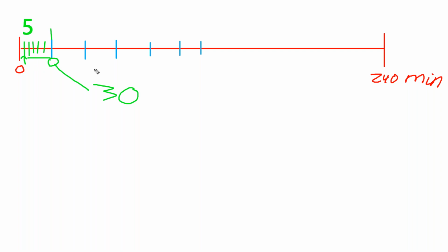What happens when a valve closes? Well, you're going to have a sudden pressure surge that is going to be reflected throughout the system. AFT Fathom with the XTS module is not going to capture that behavior, okay? It's not going to account for the wave speed of the fluid. It's not going to show you how your pressure waves are propagating back and forth throughout the system very, very quickly. It's capturing fairly slow changes in the system.